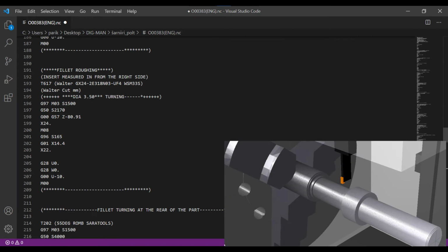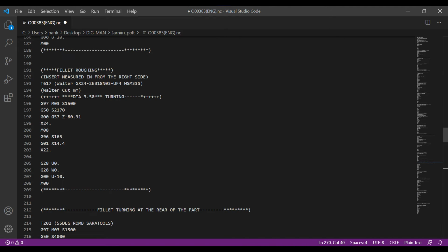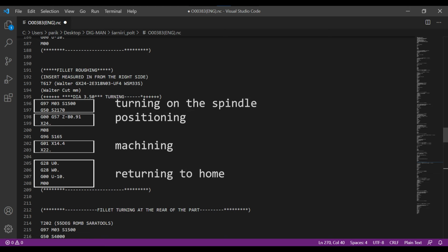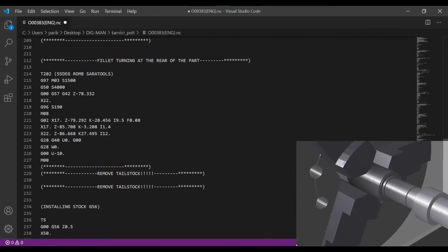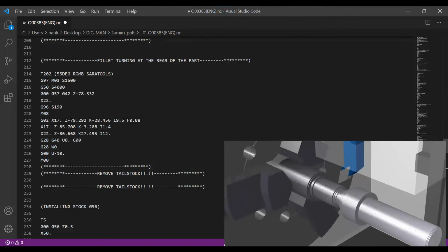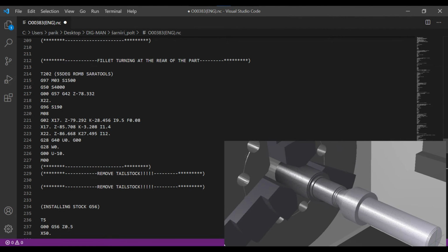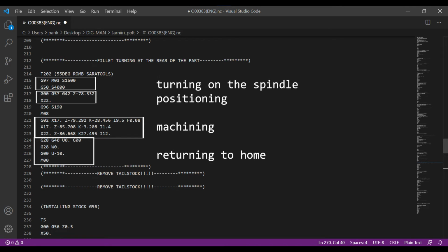We simply plunge the grooving insert to the material. The actual fillet is created with the finishing pass. Here we have the fillet finishing. Using G02 we create the desired geometry with 3 different moves. Once that is completed, we return to the home point of the machine.